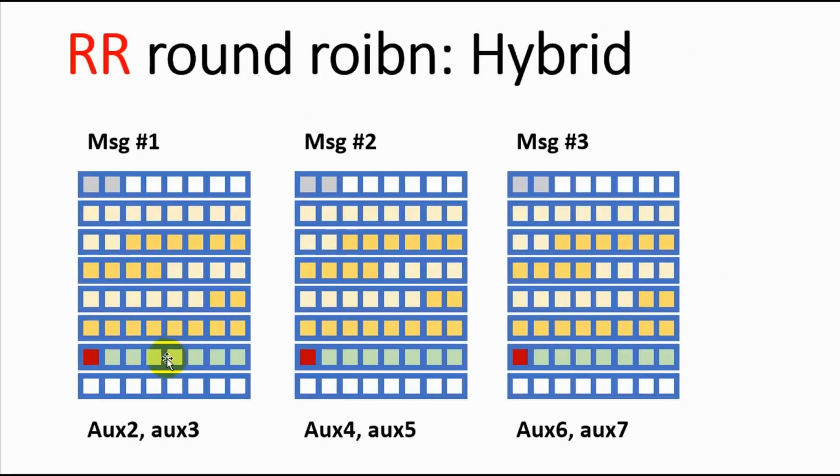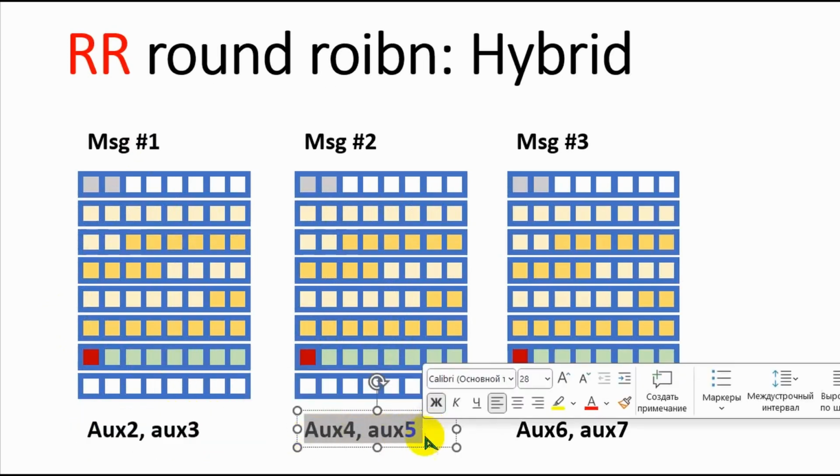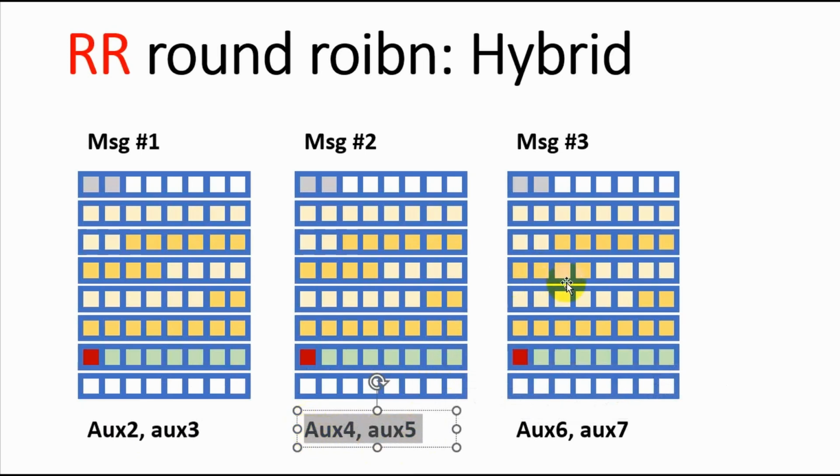Easily, it means that we don't send all the information in one message. We have number of message, and let's say in message first we send all gimbals, we send arm value, and we send, let's say, AUX2 and AUX3 only. Then with the next message we send all gimbals, arm value, and the next set of AUX. I'm not sure about this order, which channels are sent. The ELRS experts will correct me, but anyway,